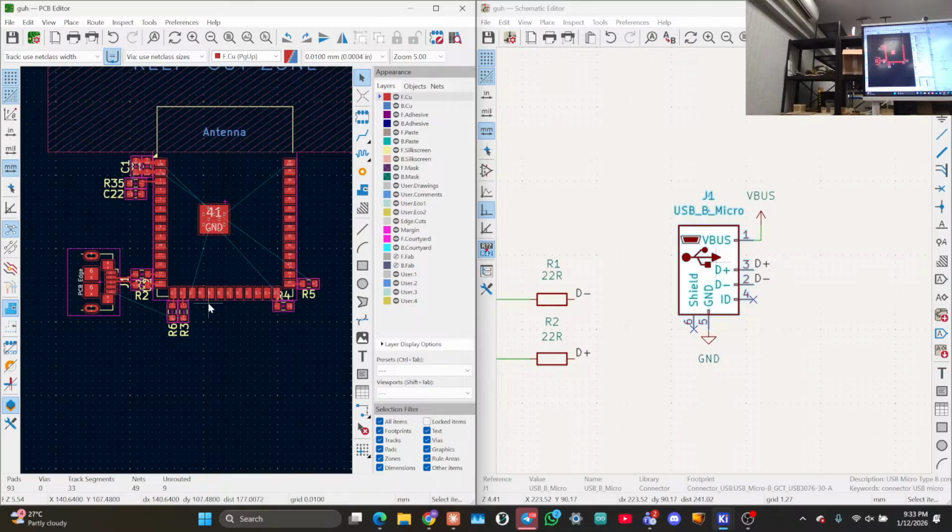Generally for routing these lines, avoid sudden sharp bends. So a 45-degree bend is fine, but you don't want too many others to happen in quick succession, you know. That right there, that's a funny discontinuity. Yeah, that's one good.